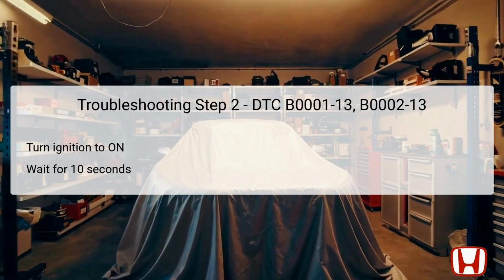Once the DTCs are cleared using the HDS, the next step requires turning the ignition switch to the on position, also denoted as position 2, or pressing the engine's start-stop button to select the on mode. This action powers up the vehicle's electronic systems, including the airbag module, allowing it to perform self-checks.